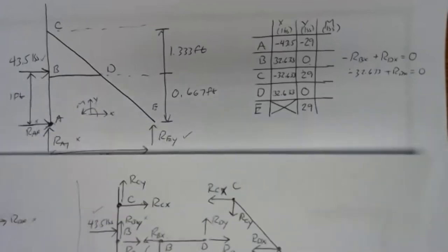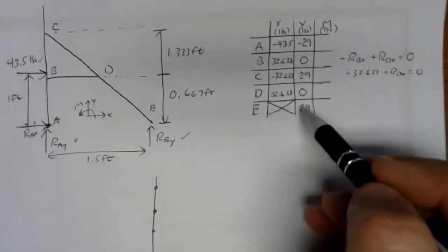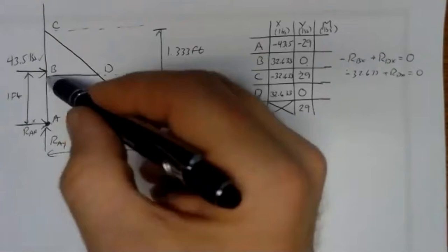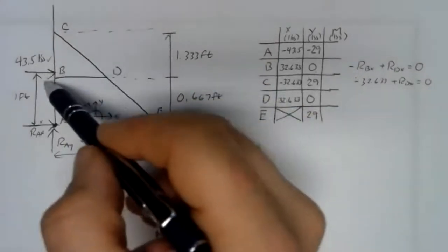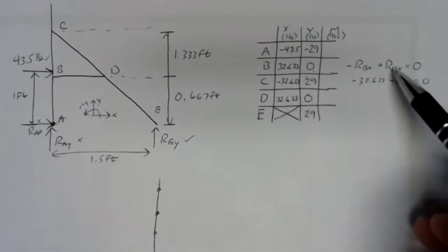We've used all 9 equations that we made up. One set of 3 from the external problem, where we got 3 numbers, our values at A and E. Then we did the free body diagram of the horizontal, which gave us 2 numbers, the 2 zeros, and an equation that we could use later.